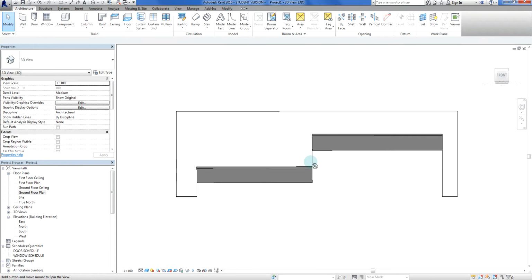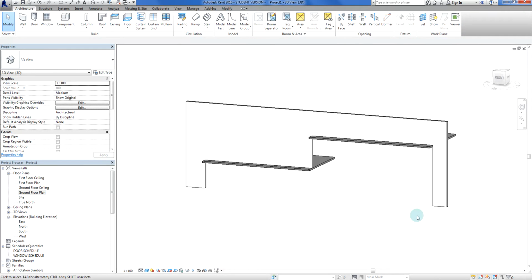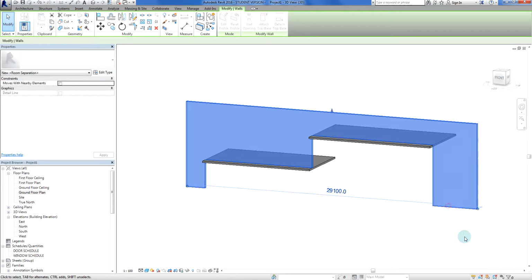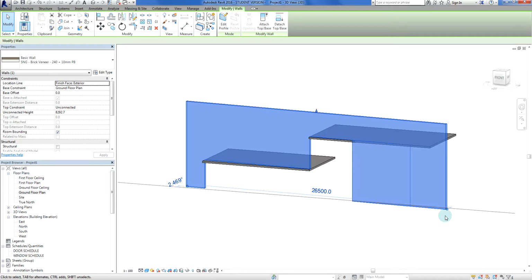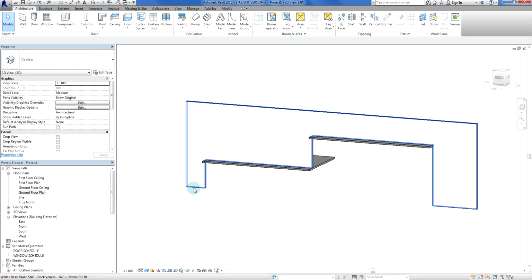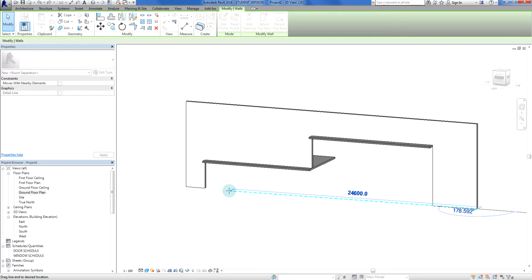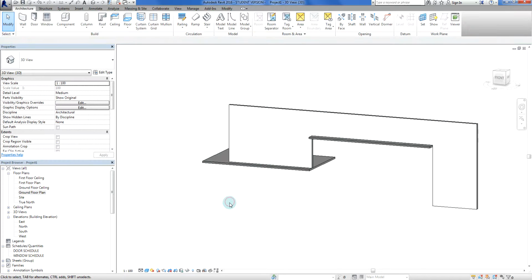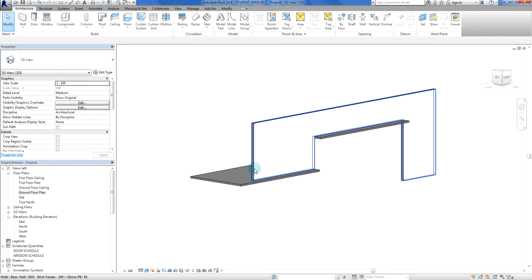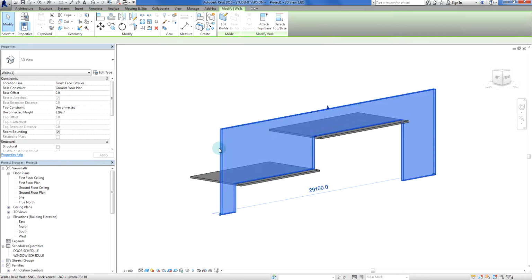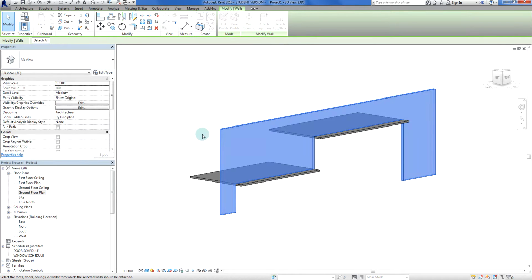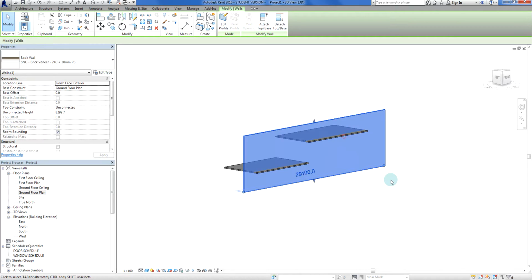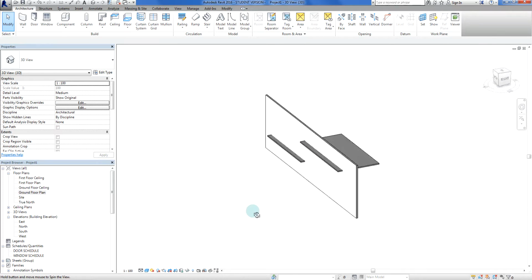But we get this nice little funky opening. And I can push and pull that wall. Oops, that one wasn't very straight. If I push on the parallel, you can still shape it, and see Revit will keep attaching it until it's told otherwise. So detach that, detach that, back to my default wall.